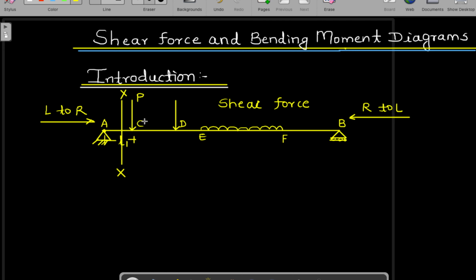And bending moment, when we calculate it about this section, say section x-x over here, you can consider your calculation from right to left, or from left to right. Say we are doing our calculation from left to right, for example only. This is not a question we are solving, this is just to understand the concept of bending moment. When I consider left to right, there will be some reaction Ra, and say this is a distance x. So bending moment at x is equal to Ra into x. This is how we take the algebraic summation of moments of forces acting on the left or the right.